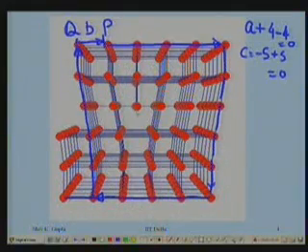What is a right hand screw notation? For the right hand screw notation, the first thing is I must decide the direction of the dislocation line. In this case, my dislocation line is right here, going inside. F point, E point, they will be visible at just one point here. It's a line inside the crystal. Okay, front is F and the back is E.